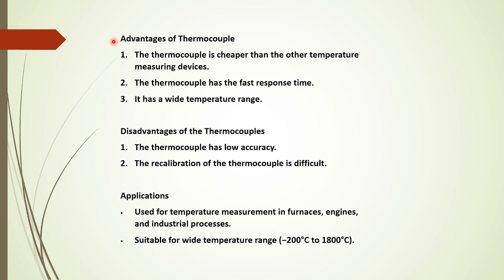Next, we go for the advantages of the thermocouple. The thermocouple is very cheap when compared to other temperature measuring devices. It has a fast response time and a wide temperature range. The disadvantages of the thermocouple are that it has low accuracy and recalibration is difficult.